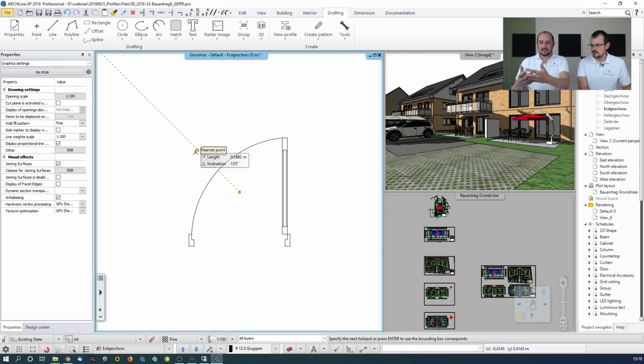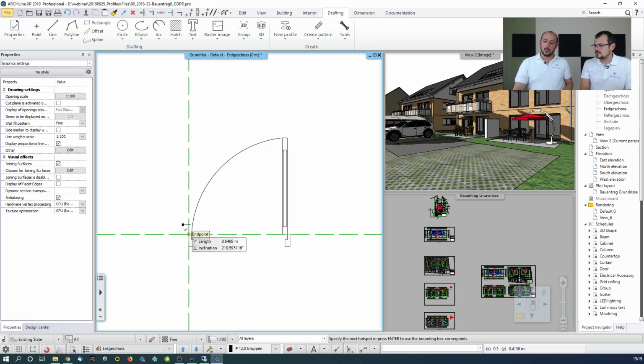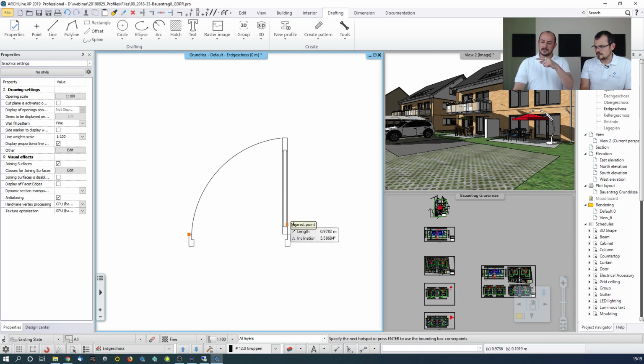If you would like to use this as a door symbol, not just any 2D symbol, then there is a very specific order in which you need to define 4 different reference points, or insertion points. That's how the door is going to be inserted onto the model that you have. This is the way the software will understand what are the sides and what is the front and what is the back of the door. So number 1 is at the left top, number 2 is at the right top, number 3 is at the left bottom, and number 4 is at the right bottom. So 1, 2, 3, 4. This is the correct order. So you just define those, and you do not define any others. You just define 4 reference points, and then you save it.